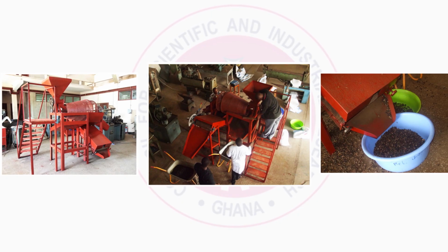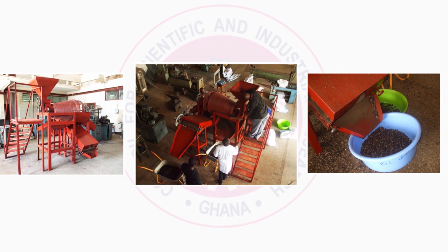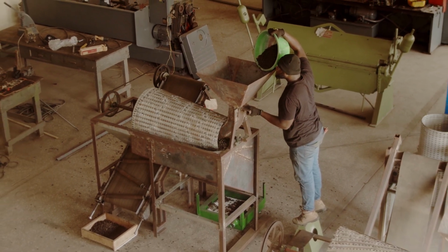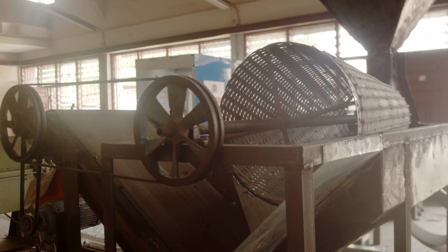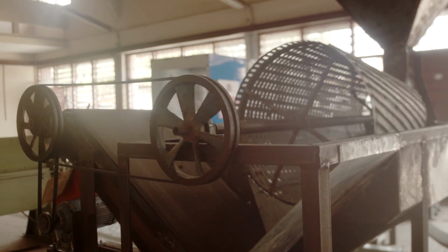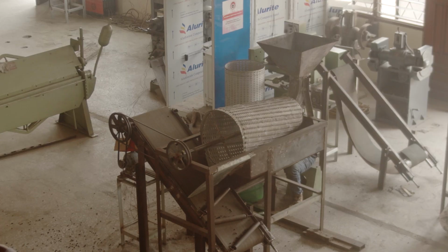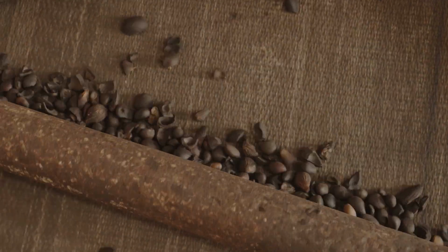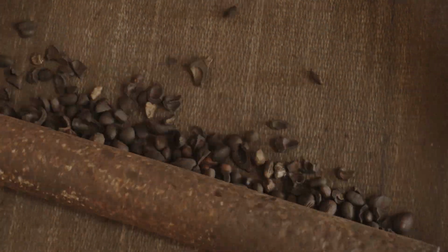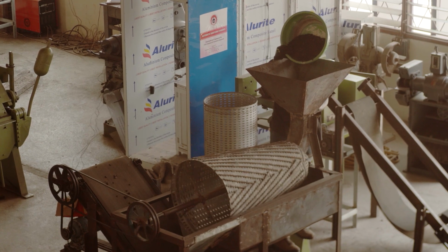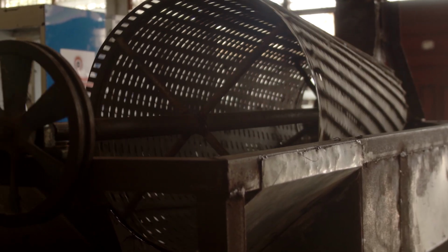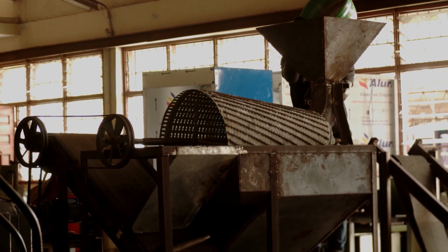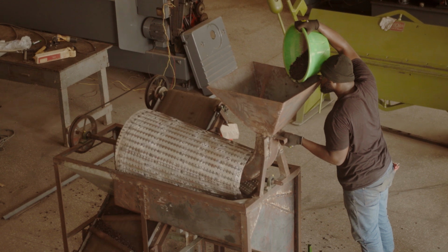It is designed to separate cracked palm nuts into various components. The design concept was formulated based on solid material separation techniques. The concept focused on particle properties such as friction, both static and dynamic, size variations, and motions of particles, as well as factors that influence friction on a given surface. A truncated concentric two-ply sieve was used to automatically grade the material being separated into two grades based on size and, per the concept, improve upon the efficiency of separation.